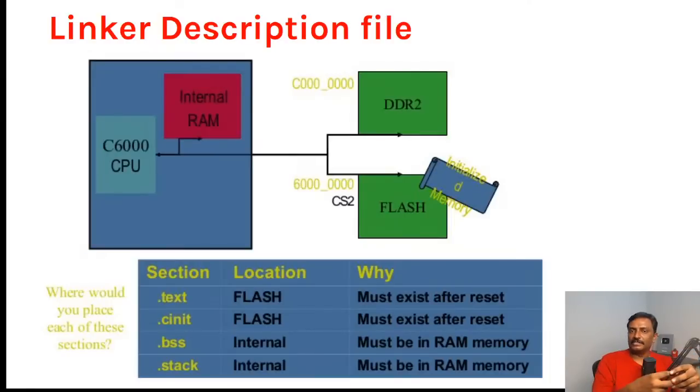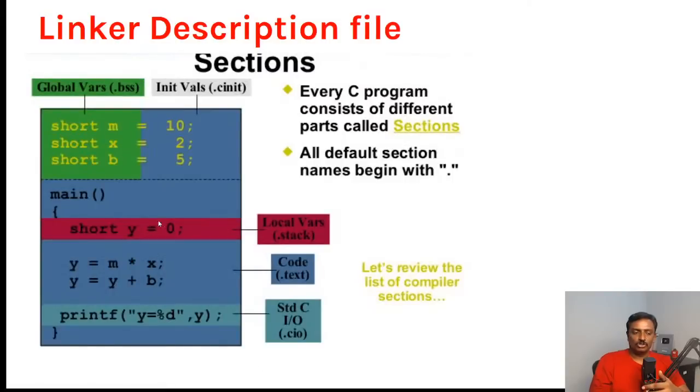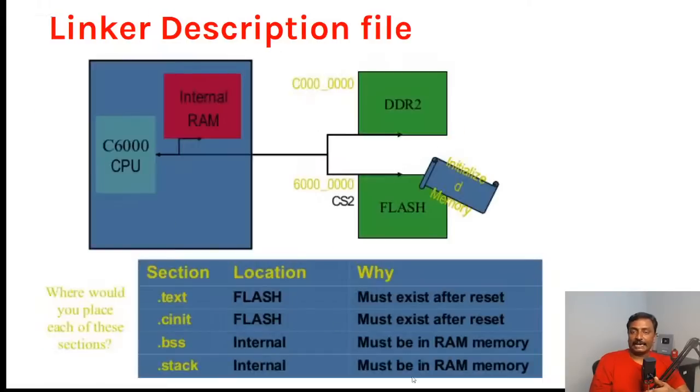The microphone will give you analog data, which you pass to your audio codec and it converts that to digital data. This digital data you have to store, and you'll be doing some noise filtering, which will generate coefficients. All those coefficients will be in local variables, so you could put them on the RAM.